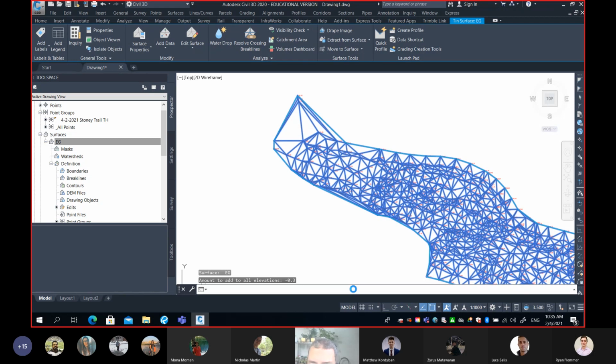Over the years, maybe you left the wedge in the office, maybe it is lost. What people do is they simply use a rod minus the wedge, so the wedge is missing. So all their elevations are wrong by a constant offset, which is simply the length of the wedge.